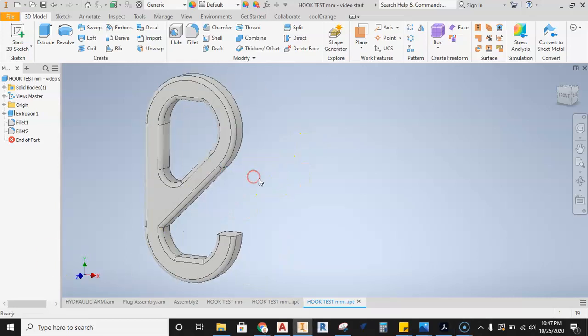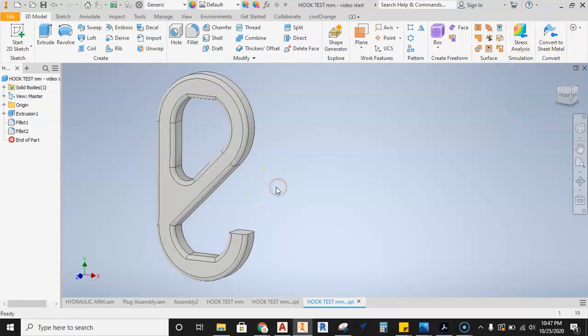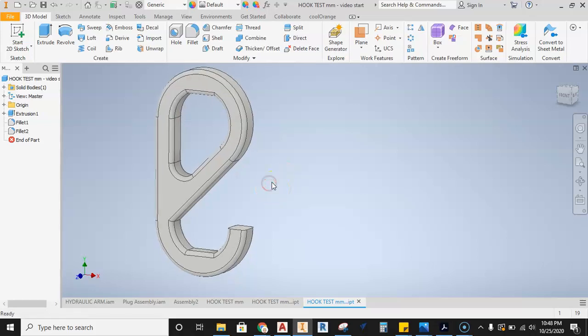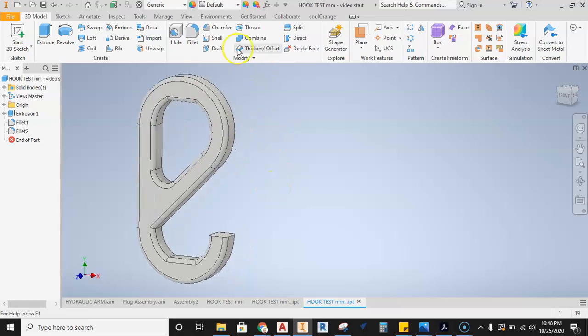All right, in this video we're going to talk about how to set up the finite element analysis or stress analysis in Inventor. And this is a real basic how-to. This is by no means a full explanation at all. But to go ahead and set this up so you can actually run some tests on your parts, the first thing you have to do is go ahead and assign your materials.